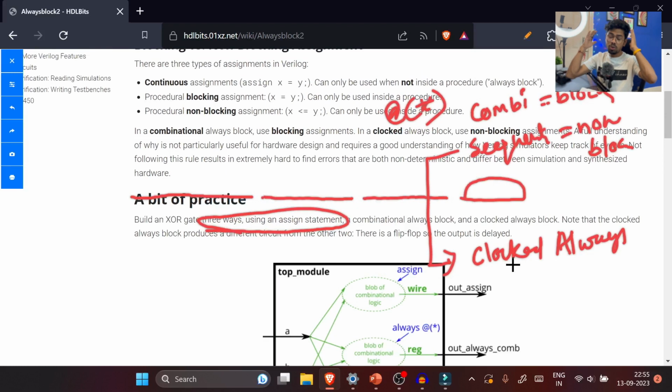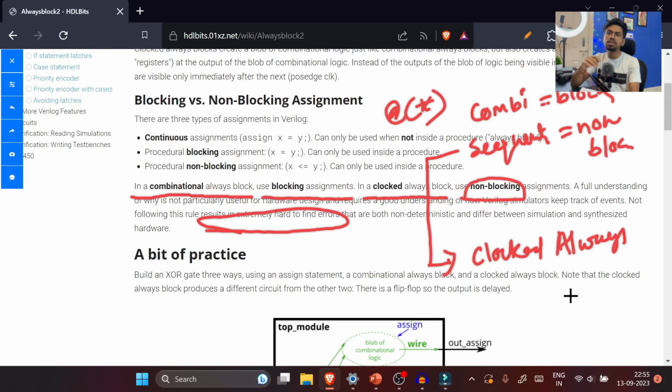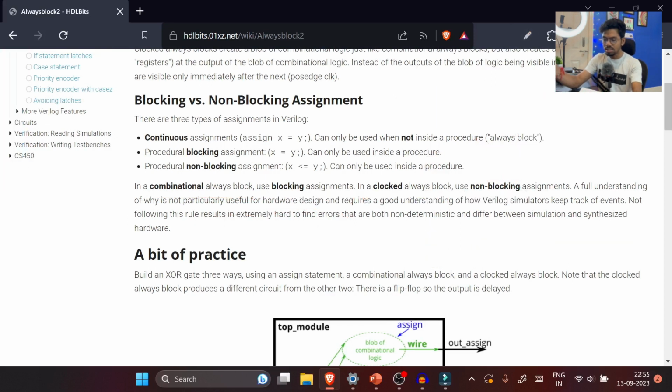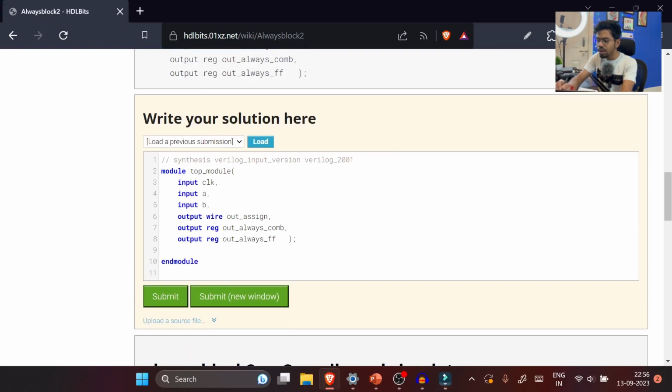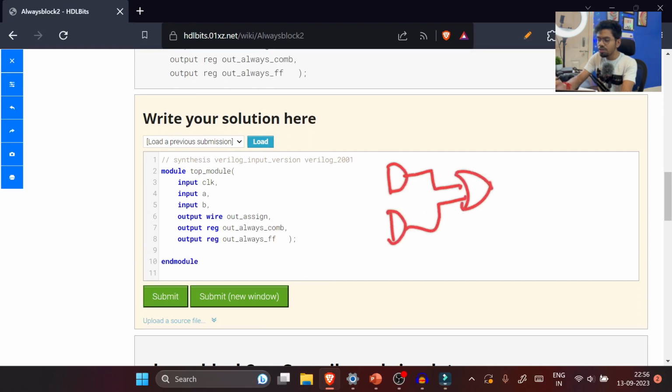Now the question is, what's the difference between a sequential circuit and a combinational circuit, so that we are having this much discussion. For that I need to write something here. Take this example. Here you have one AND gate. Okay, let us take two AND gates, and both of these go somewhere, and then we have an OR gate, and we are getting our out here. And here we have A, B, C, and D. This is a combinational circuit.